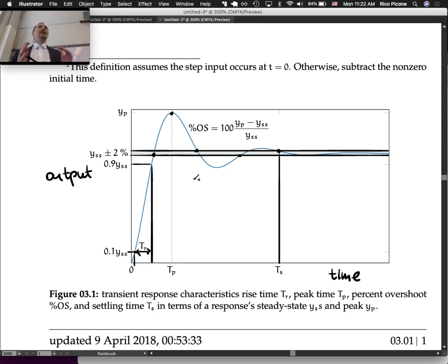So there are some cases where you can deal with a little bit of overshoot, others you can't. Say you're positioning a robot arm from this position to that position. A little bit of overshoot might not be a big deal in that case. Maybe you care about it being fast instead. But maybe you're doing robot surgery, in which case you probably don't want that overshoot. At least not on me. No, thank you. Okay.